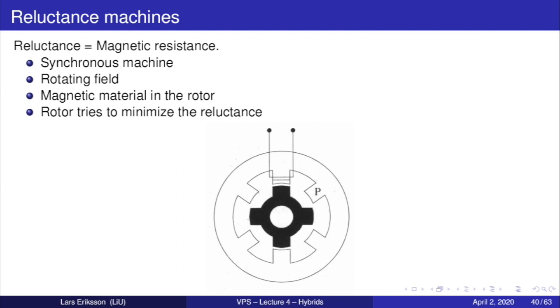Another machine is a switched reluctance machine that is rotating with the aid of the reluctance effect. The basic principle is that when we have magnetic material, it tries to align as much as possible to get the best reluctance, so we have the best magnetic flow. The way it's controlled is we're magnetizing this part here and it aligns like this.